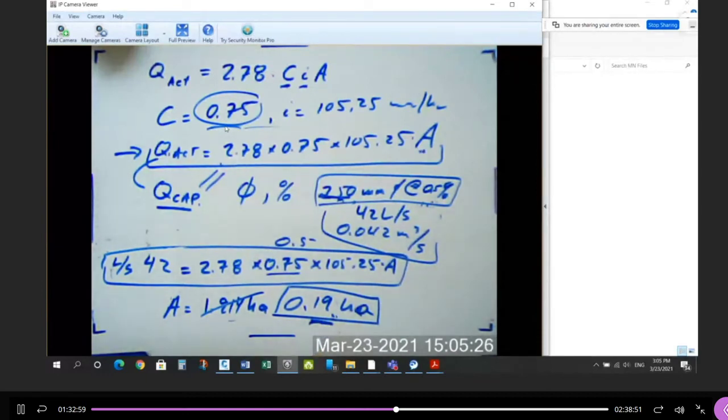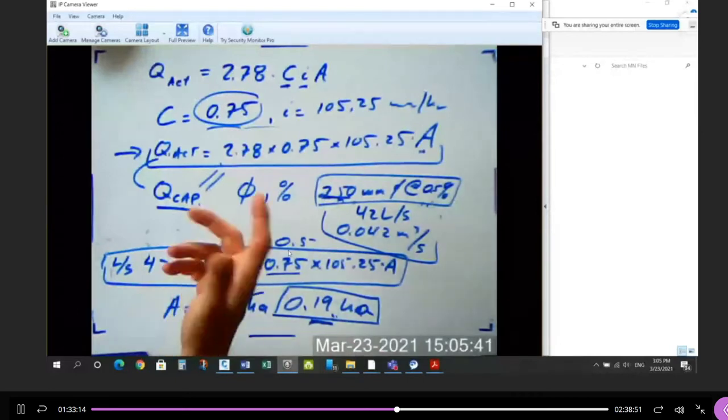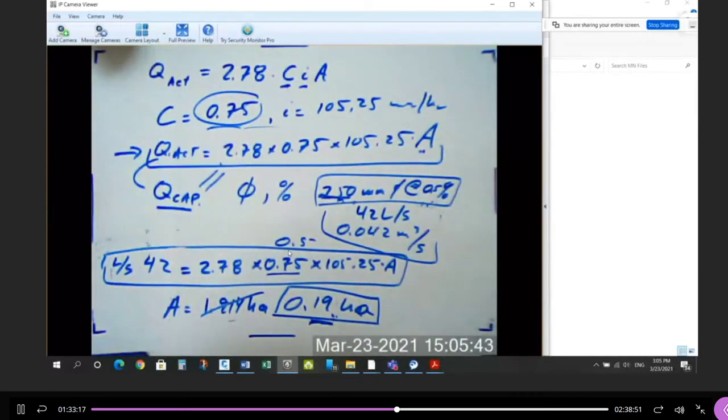So basically what you do is you convince yourself that the generic size you want to use, a 250 at 0.5%, will do for any rear lot catch basin. Okay, so this calculation, and some of the stuff I erased, right? This calculation you would keep in the project file. It's a hand calc, right? You would keep this in case somebody questions it.